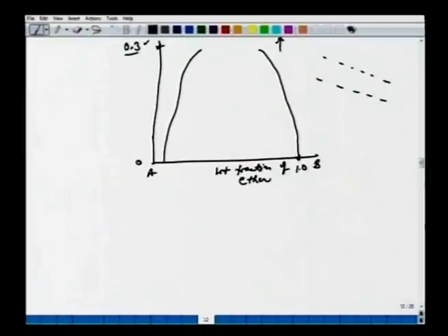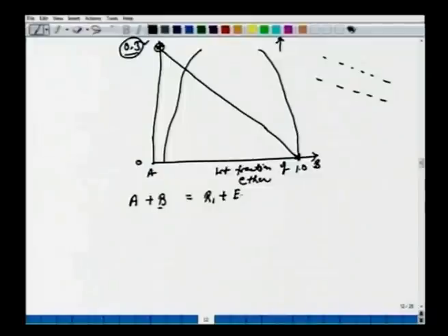So this is also very important, that we realize that the rest of the data we don't need, so that we can expand our scale and we can work in this range. Now the feed for the first stage is 0.3, and it's a pure solvent. So this is 1 here, we connect, so we are mixing in the first stage, and we mix and then we settle. So knowing the amount of this 0.3 and the amount of the solvent, we can write A. So let's say for the feed, solvent added here gives us R1 and E1, raffinate and extract phase, they are in equilibrium.